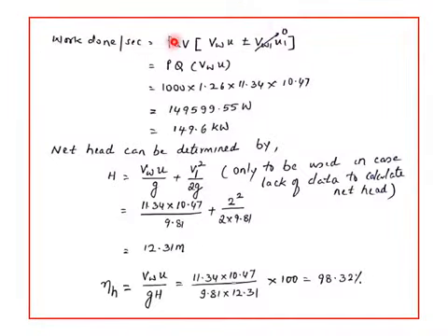Now you can calculate work done per second. Since the discharge is radial, Vw1 will be 0. So A into V is Q, so 1000 into Q, which is 1.26, into Vw into U, which are known. Dividing by 1000, we get 149 kilowatts.